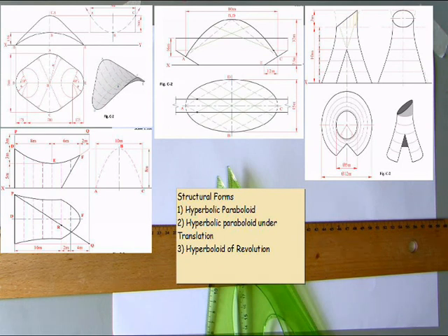I like to call that the perimeter method, where you have a 4-sided figure in one of your views, and you have to translate that 4-sided figure to your other view, and you're given a limit for your perimeter of your object, and that limit on the perimeter of your object then is transferred to the secondary view, and sometimes you're asked for a third view for that.